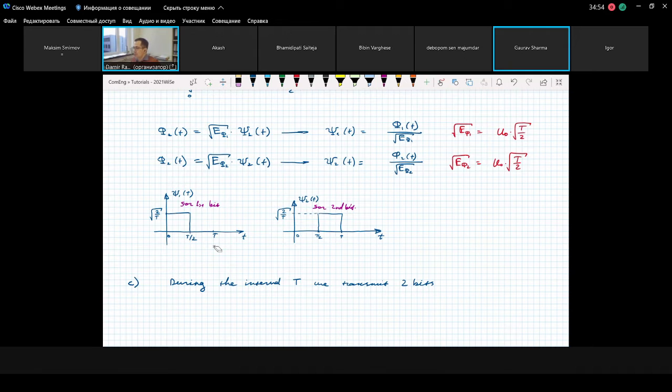You always have a general procedure, the Gram-Schmidt orthogonalization procedure, and always in your mind, you perform this procedure. But of course, you don't need to show it explicitly, because when you do it, you can take some shortcuts. And for the Gram-Schmidt orthogonalization procedure, what do we say? Take your first signal as your first basis function.